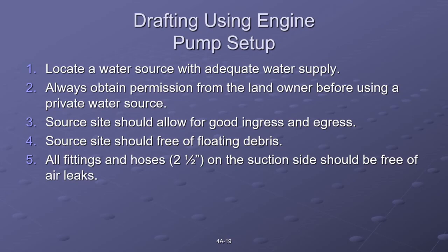In this case, we're talking about pumping water and drafting it from a source and pumping it into my tank. So locate a water source with adequate supply. Great. Always obtain permission from the landowner before using a private water source. That's policy. It's debatable. I'll touch on it again later. It could be argued that you don't have to do that in some locations, but generally it's a lot better than staring down the barrel of a shotgun. So I like to ask.